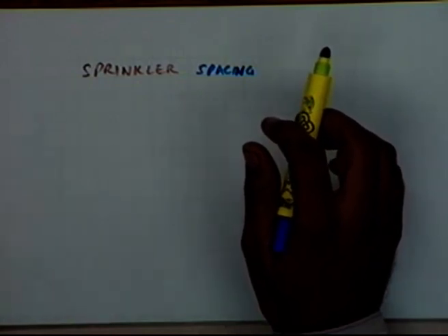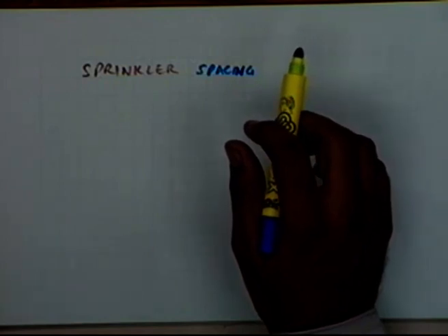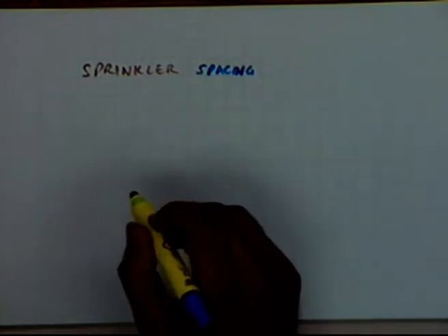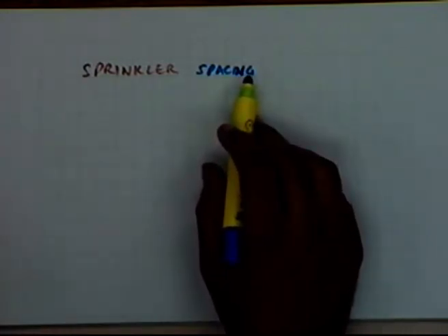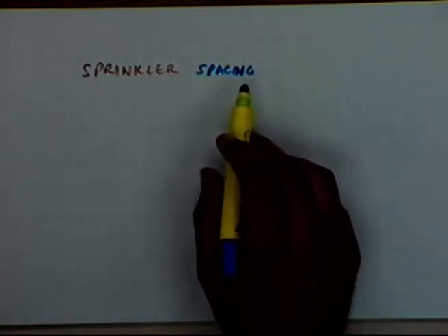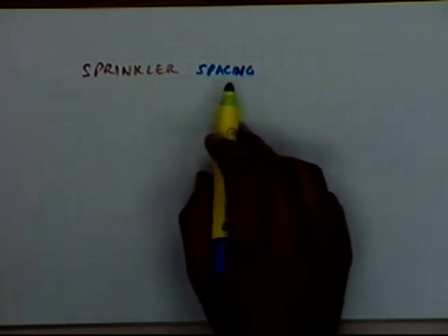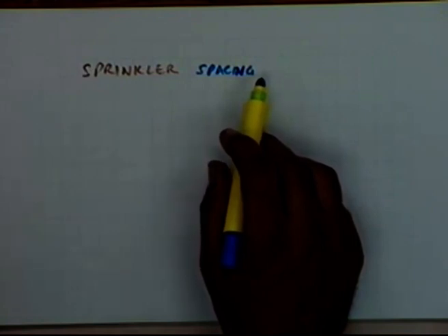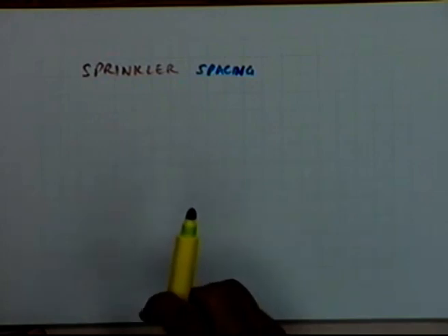The sprinkler spacing is the one which can be manipulated. The sprinkler spacing will also be important when you are trying to incorporate the wind conditions. Again, you want to alleviate all the ill effects of the wind conditions through the proper choice of the sprinkler spacing.